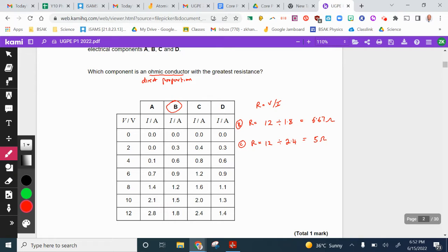So that's 0 to 0, 0 to 0.1. That's not equal jumps. And again, because that's not an equal jump from there to there, that does not obey Ohm's law. B, you've got 0 to 0.3, that's add 0.3, and that's add 0.3 again, add 0.3, add 0.3, add 0.3, add 0.3.